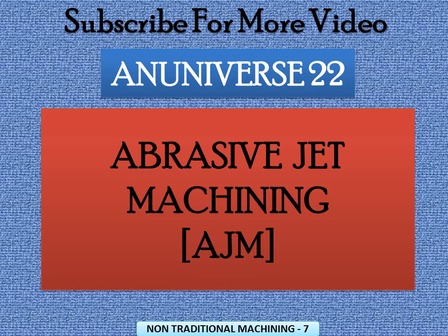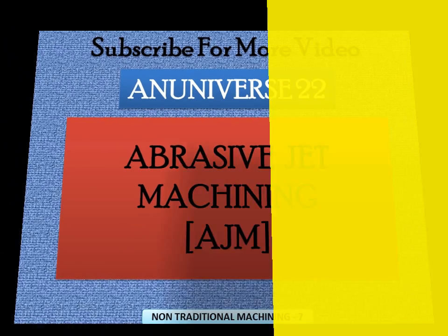Today we will learn about abrasive jet machining. This process differs from sandblasting in that abrasive jet machining has smaller diameter abrasive and a more finely controlled delivery system. And workpiece material is removed by mechanical abrasion of the high velocity abrasive particles.